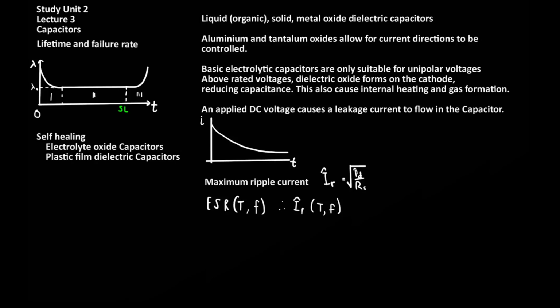A common failure mode in capacitors is when the applied voltage across the device terminals exceeds the rated voltage of the device. When this high voltage is applied, there will be defective areas inside the dielectric which will experience abnormally high electrical fields. In these high electrical fields, arcing will start to happen, which will further damage the dielectric.